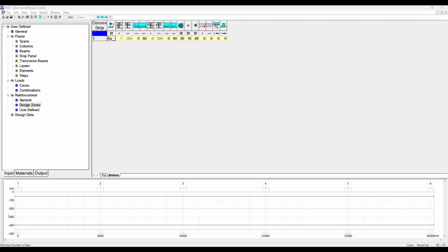When RAPT designs the reinforcement, it will tell you what the required development is at the end of the bar. So it may say to you that there is 0% development required. In other words, you can put the bar there and the bar will develop gradually over the length. Or if it says that you need to have developed, say, 50% at this point, then that means you must put a cog in at this bar location. That'll make more sense when I go into user-defined reinforcement, which is here.